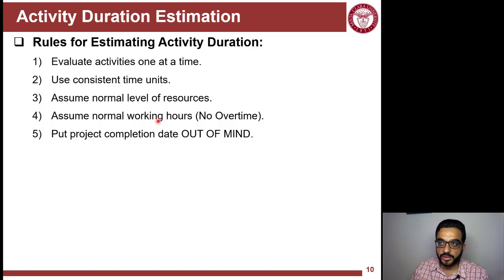If you end up with 0.1 day, it's a decision you have to make. You can round it up to a day to have the minimal 1 day in your schedule, or you can add it to another activity, and when they add up, they will add up to a day, instead of wasting 0.9 and 0.8 days embedded in 1 day durations.